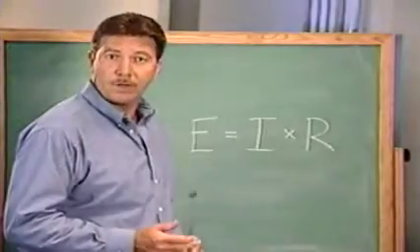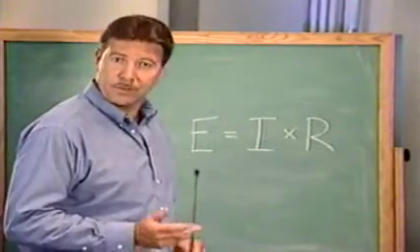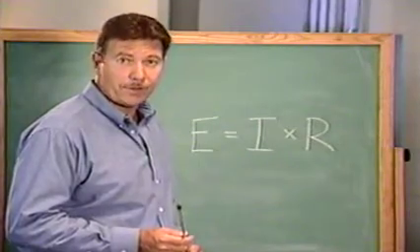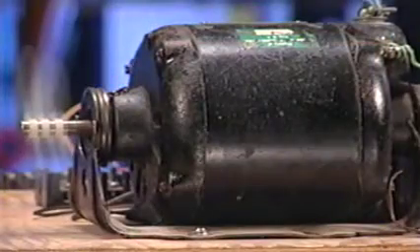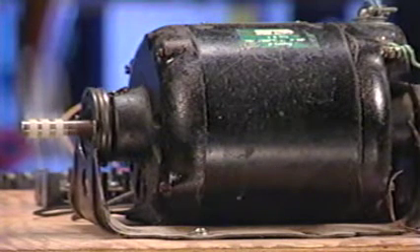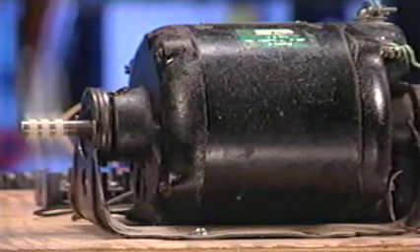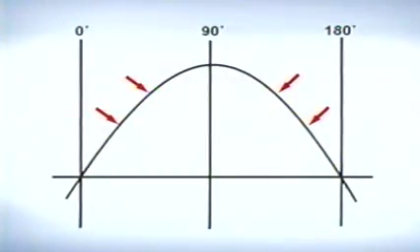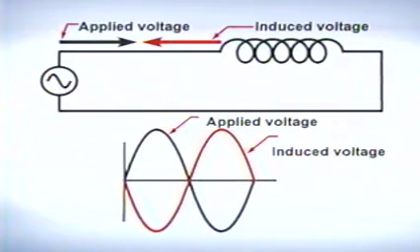From an earlier discussion of Ohm's law, we mentioned that there is a predictable relationship between voltage, current, and resistance. This relationship is somewhat altered when we deal with AC current flowing through circuits that have inductive loads, such as motors or solenoid coils. The changing voltage in an AC circuit leads to changes in the strength of the magnetic field as a result of Ohm's law. These changes in the magnetic field produce a second voltage called induced voltage, which counteracts the effects of the original supply voltage. The supply voltage must first overcome this induced voltage before current can flow.